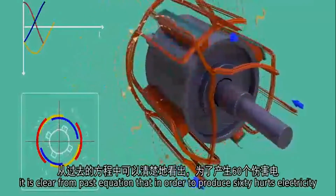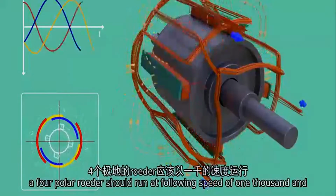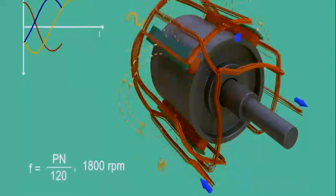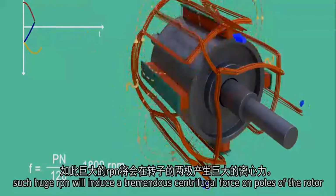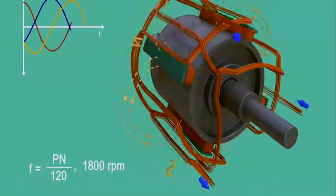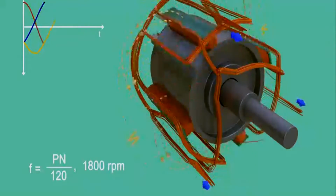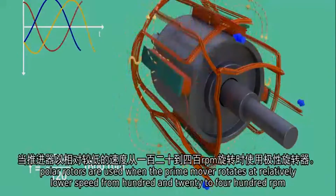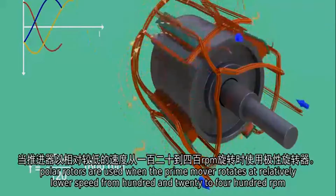It is clear from past equation that in order to produce 60 Hz electricity, a 4-pole rotor should run at following speed of 1800 RPM. Such huge RPM will induce a tremendous centrifugal force on poles of the rotor and it may fail mechanically over time. So salient pole rotors are generally having 10 to 40 poles, which demands lower RPM. Salient pole rotors are used when the prime mover rotates at relatively lower speed from 120 to 400 RPM.